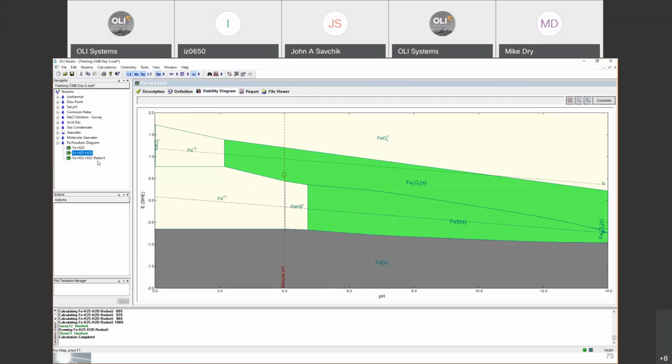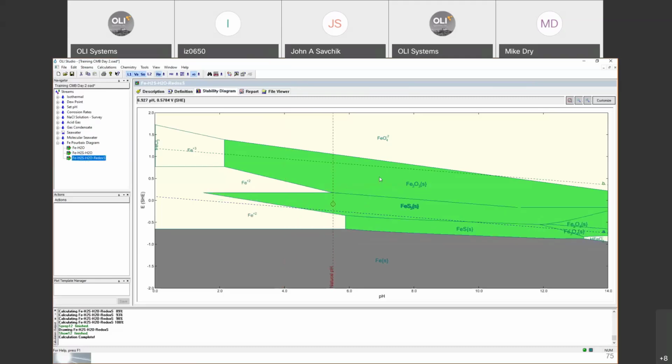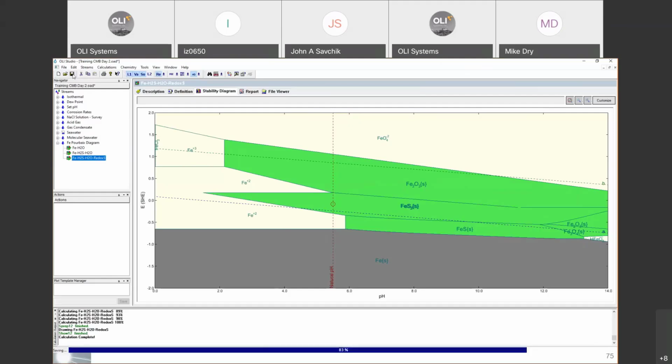And if you keep in mind that if you include both the elemental sulfur and hydrogen sulfide, now this is what is being formed: pyrites and hydrogen sulfide, probably mackinawite, and this phase up here. Okay, you have even more protection because now you are going to lower pH values. So that is with regards to the Pourbaix diagram.